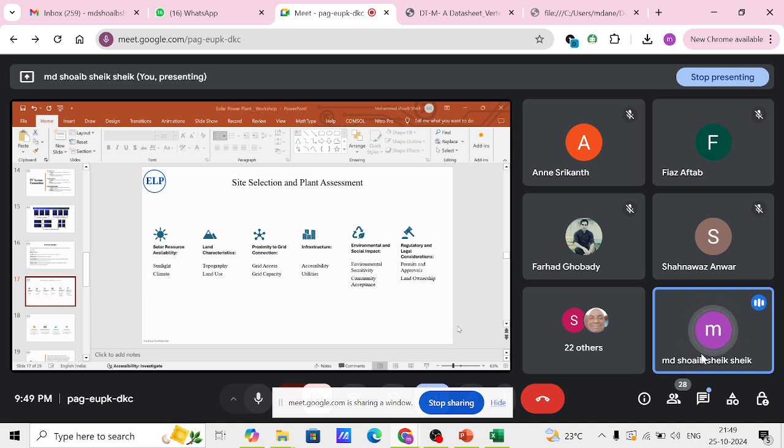See, I have a substation somewhere of the grid company. If I'm installing this somewhere, the wires have to go through some different places, where different landowners will be involved. So, is everything fine, is there no issue with them? You have to check, take the permits and approval, and pay for that, then only can you install the system. All these things come into the feasibility.